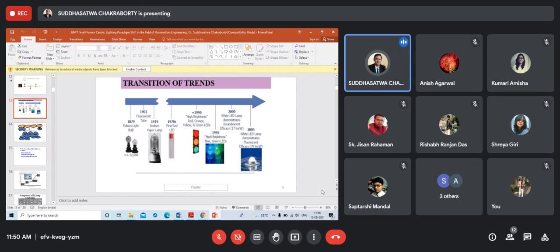But the issues were very much there, because the number one issue was the life of the LED. Within 1.5 years, suddenly the light output became 30%. That was a great challenge. But the only reason that 5 millimeter white LED became so popular is that it was very much used along with the solar system. It will be driven by a low voltage, by the battery, so you have enough flexibility to control it.